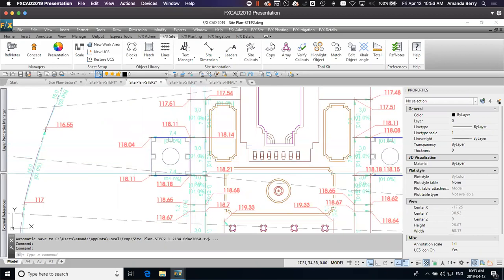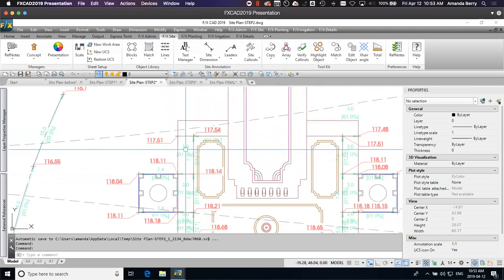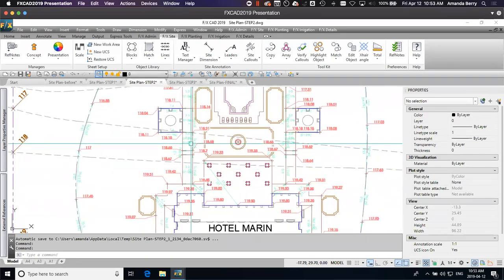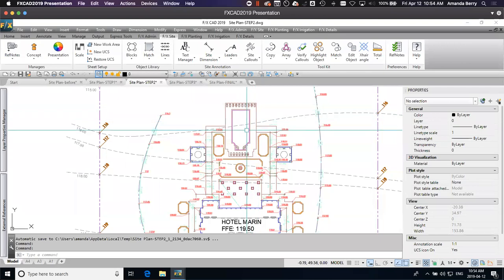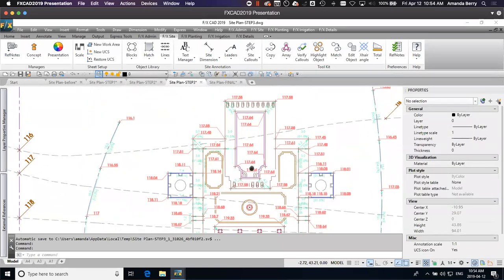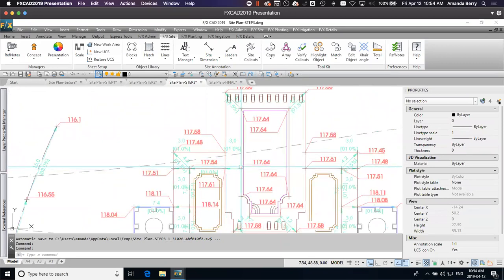I wanted this to be relatively flat to correspond with the seating area and pavilion. And then I went down, and that basically created a pinch point around here of how quickly I could grade down this ramp to get to this pool, because I didn't want to have this pool too far off of existing grade. So I basically followed that around and was able to grade up at 1% to make sure everything was flowing around the pool, and made every point in my pool the same elevation, and then just made sure I was grading away from it.